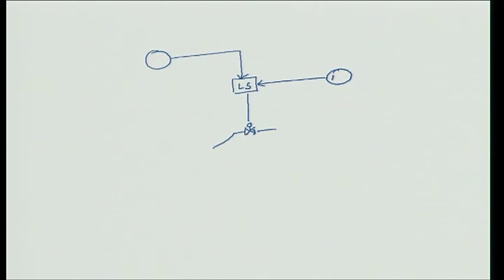Let us say there is a PI controller number 1 and a PI controller number 2, which is controlling something. It is not really relevant what you are controlling, but it is clear that this valve is being adjusted to maintain either this or that, depending on which signal is greater of the two. Both of these controllers are PI.